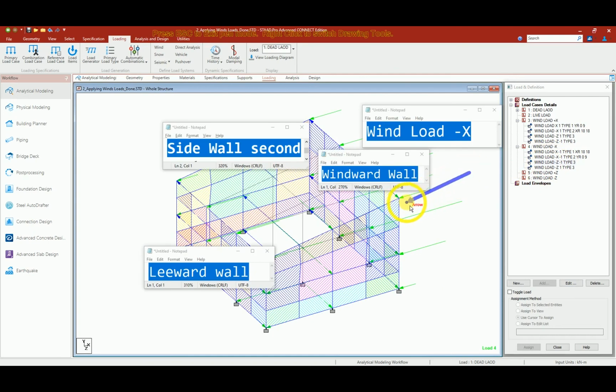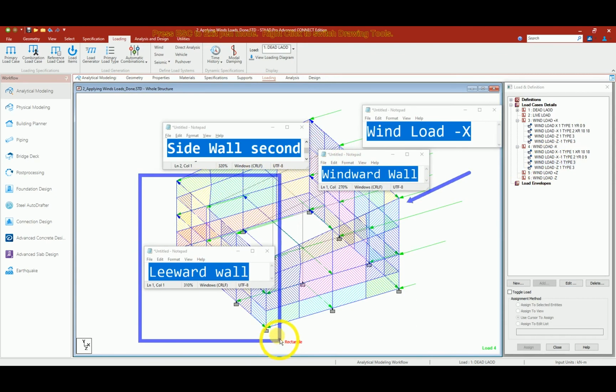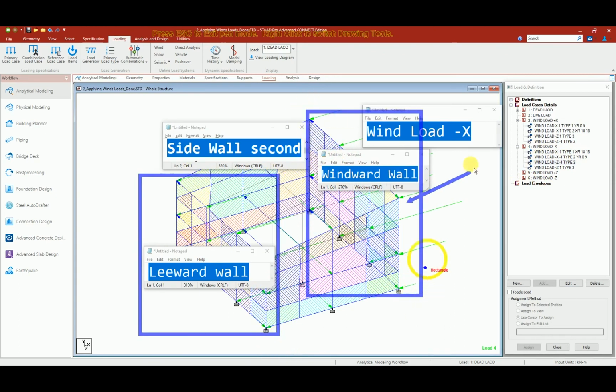So when wind flows in -x direction, the back wall will get more force, the front wall will get less, and the side walls on both sides will get forces from inside to outside. This seems correct.